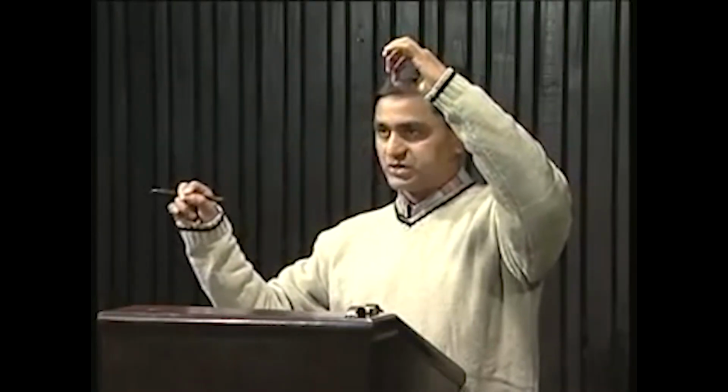So here we know the distance along the line, which in our last lecture we called x, and this particular distance perpendicular from the point, we call the offset. So by measuring this perpendicular and this distance, we can plot this point with reference to these 2 points. So we can plot our details that way.